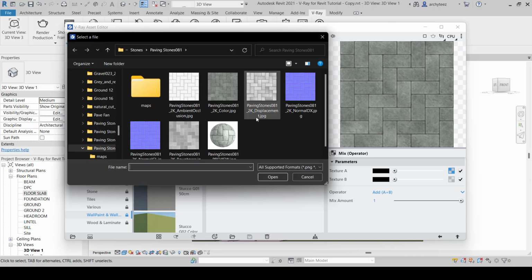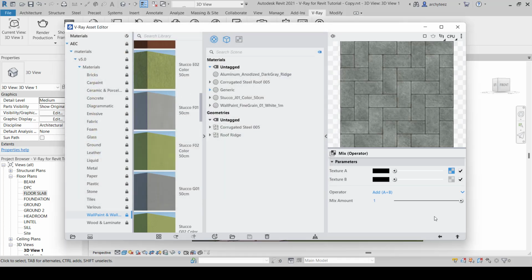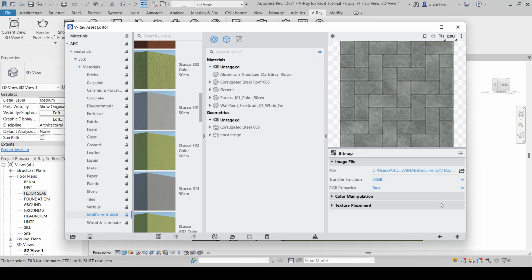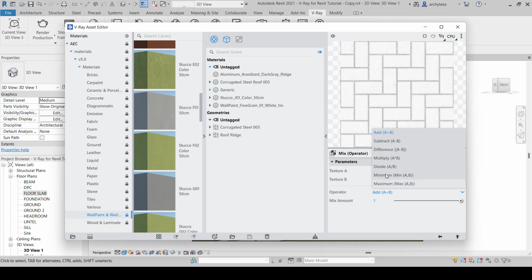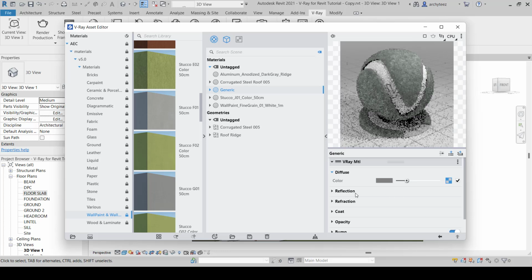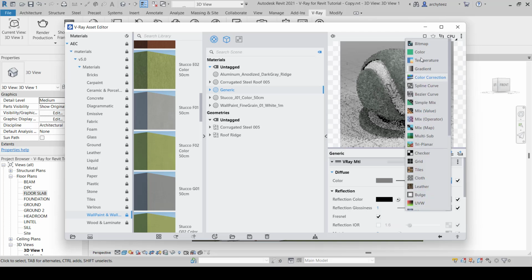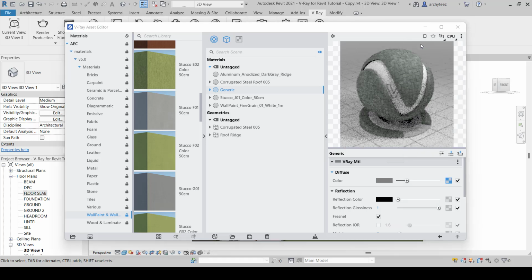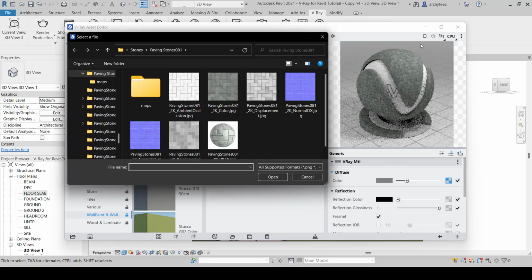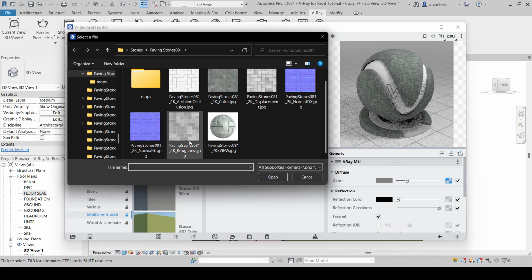Then ambient occlusion. Some other places they might just write AO. It is ambient occlusion. Find it. Once this has come in, I will just click on multiply. So go back, come into my reflection. I will come here because the reflection map I have for this is roughness. So I will look for roughness here. This is roughness.